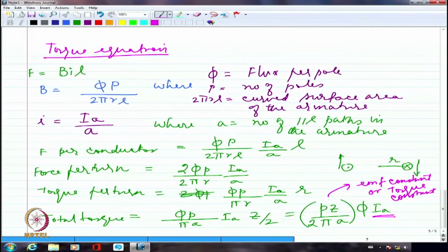If it is a motor or a generator, it will indirectly tell you the maximum current you can draw from the machine, and the voltage it can generate if it is rotated at rated speed with a given excitation. That is known as the nameplate details. The nameplate will carry the rated voltage, rated current, rated speed, rated flux or rated field current, and, for example in a DC machine, the power rating. All these things are normally written on the nameplate of the machine, right?